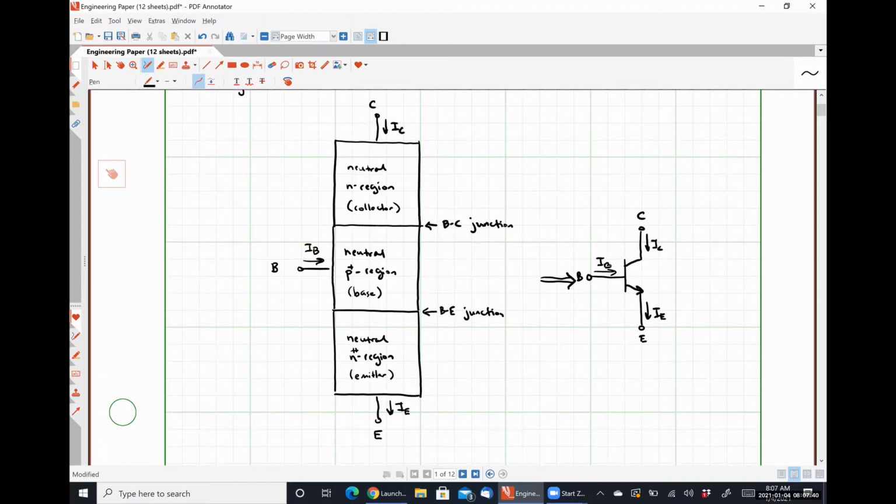The potential difference between the collector and the base, we're going to call VCB. So it's simple double subscript notation, where the first subscript is the positive polarity terminal, the second subscript is the negative polarity terminal. That then gives us here between the base and the emitter, VBE, and finally between the collector and the emitter, VCE. And notice on this particular guy, this is for what's called an NPN BJT. The arrow is pointing out. Okay? When we discuss PNP BJTs, the arrow here is pointing in because the base current flows in the opposite direction. That's all that really means.